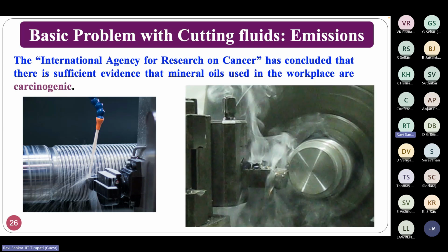I am only speaking this because this is my MTech project actually, which I did at IIT Kanpur. So obviously you can hear that I am speaking a little bit of Hindi. Okay. So when such emissions are coming, where do they go? First and foremost is the system. System means the operator and adjacent operators. So you are bending over a lathe process. Normally you bend and you just do the operation. So you are welcoming these emissions through your nose. If you are talking, through the mouth, and otherwise you can also splash this cutting fluid on your skin.